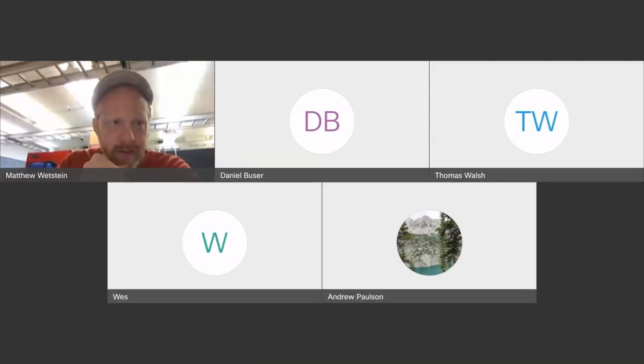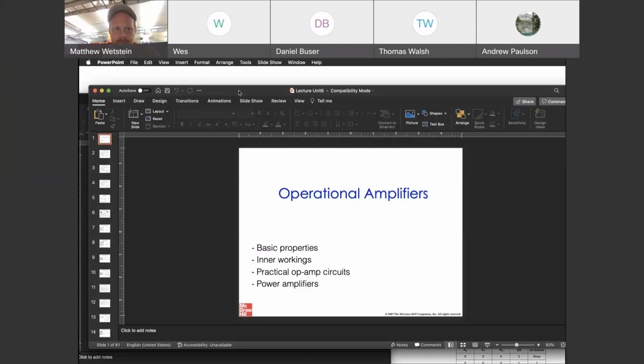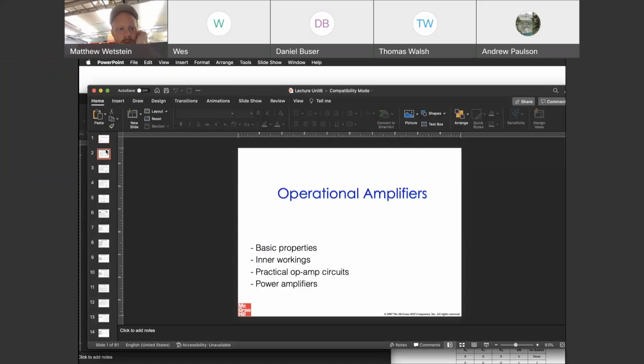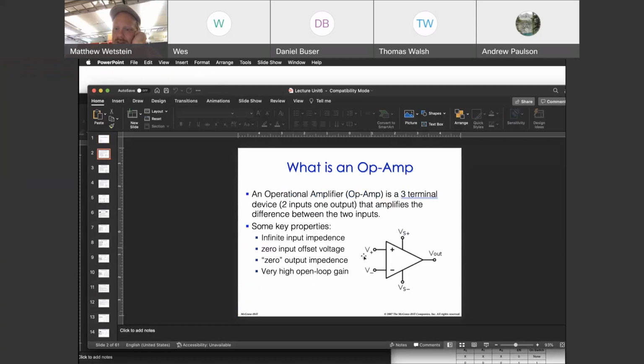Operational amplifiers. Can you guys see that? So know what one is, know what the diagrams look like. You'll notice that on Multisim, you could select a 3-pin or 5-pin. What that means is 3-pin means you're going to pretend that somebody else figured out how to power it, but that it's being properly powered and you're only worrying about the 2 inputs and the 1 output. 5-pin means in the Multisim circuit, you're actually going to worry about how to apply power to this, and you're going to design the power bus.